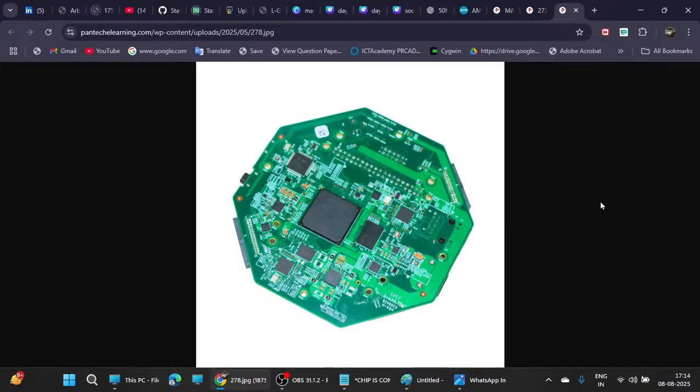If you give the inputs to your chip using the FPGA, it is good for testing, because we can control the FPGA. So we can give controlled input for the chip. Based on the inputs you get the output, and then you can verify whether I am correctly receiving or not. So this is the way FPGAs are used for post silicon validation also, to verify the chips.